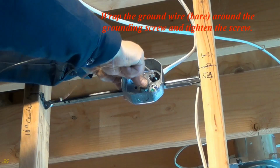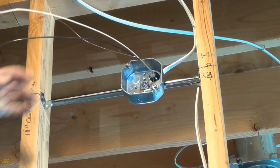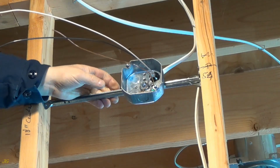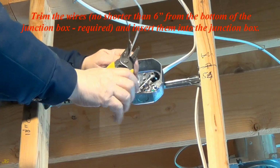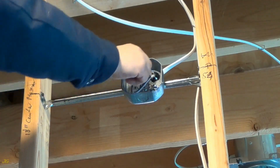Wrap the ground wire, bare, around the grounding screw and tighten the screw. Trim the wires, no shorter than 6 inches from the bottom of the junction box, required, and insert them into the junction box.